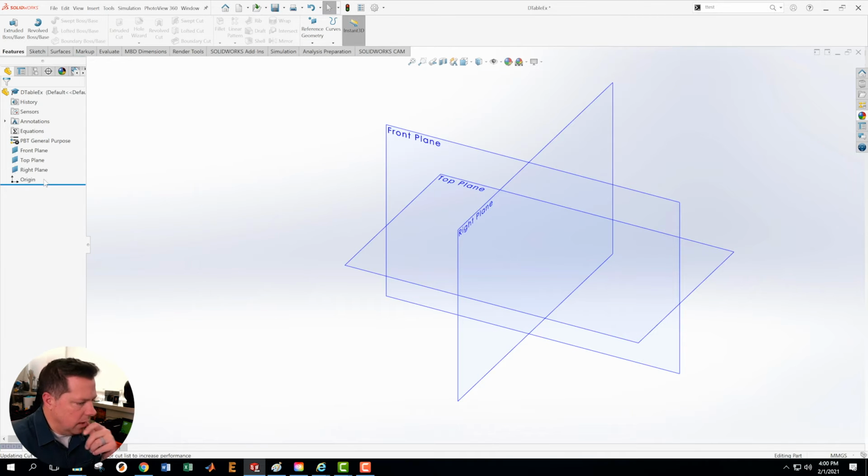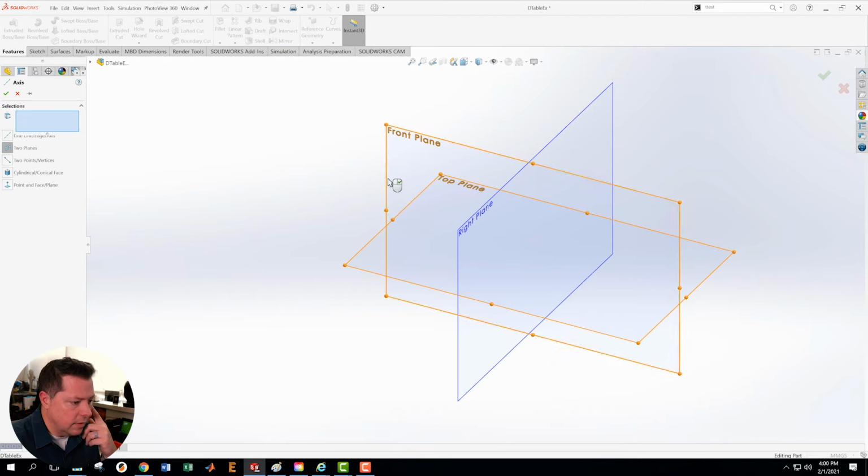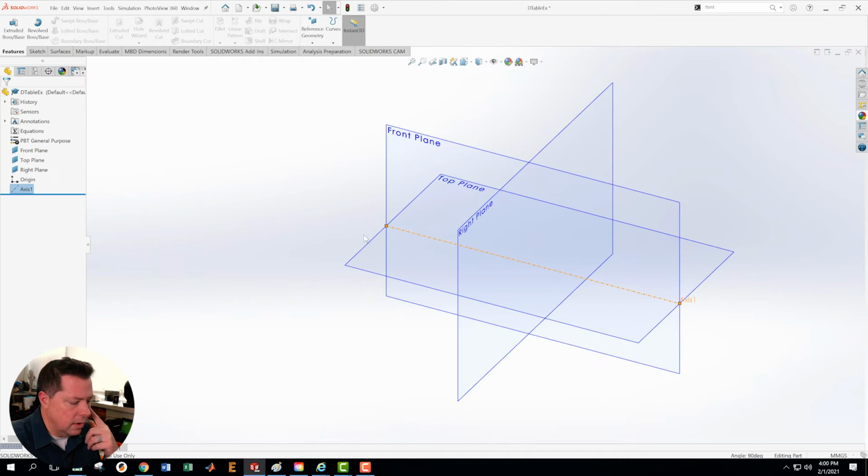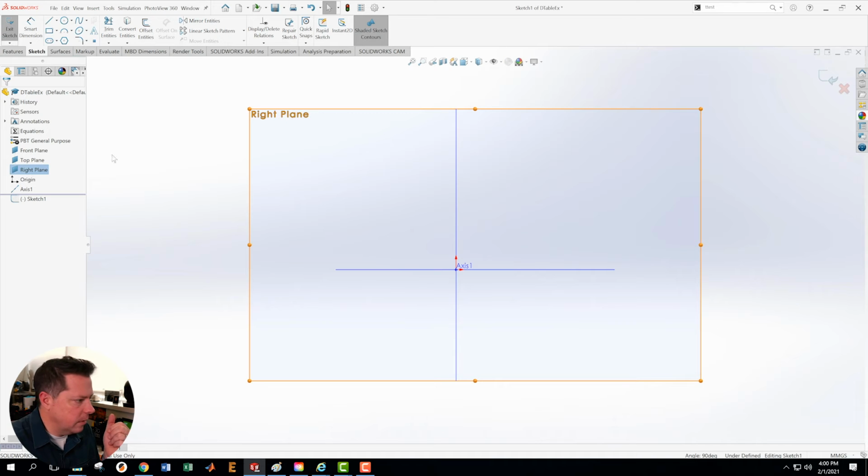Close. All right. Now I also know that I'm going to create that groove, as I mentioned a minute ago, with a revolve cut. So I'm going to start my model by getting myself reference geometry, putting an axis that I'm going to use later for my axis of revolution right down that middle. All right, so now I'm going to create my basic default part.